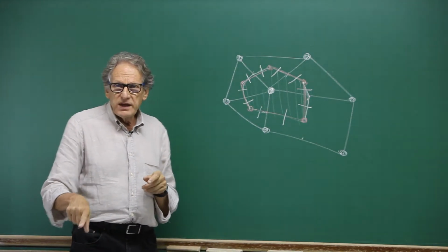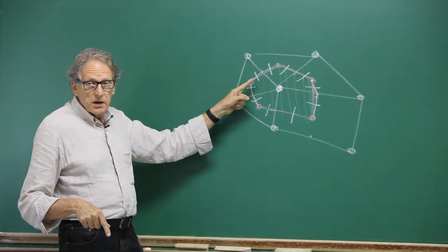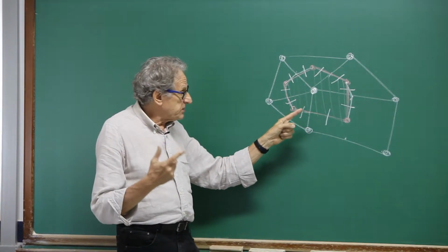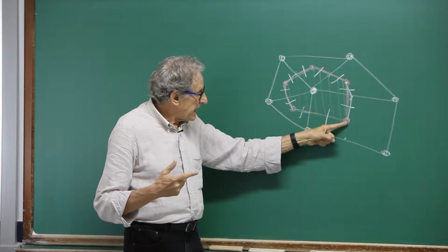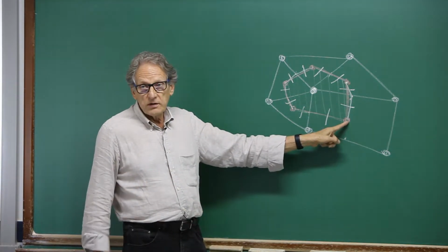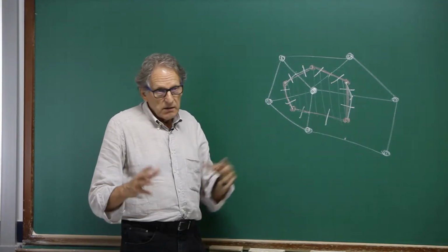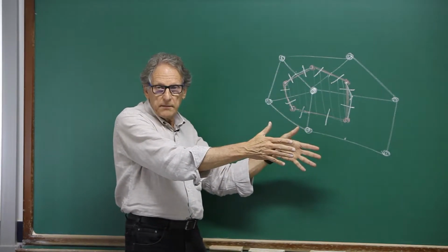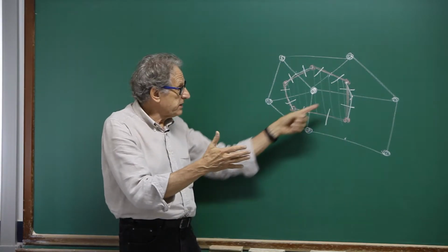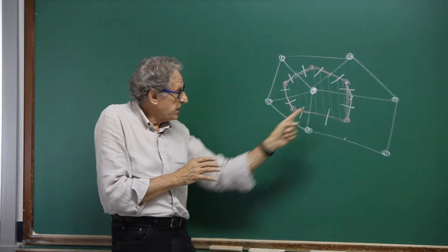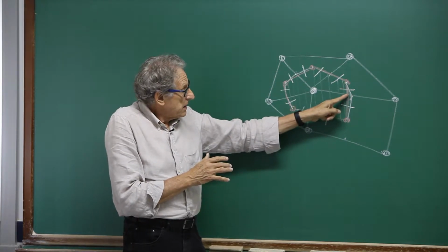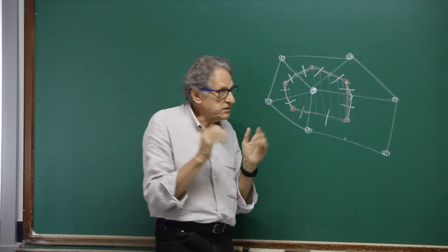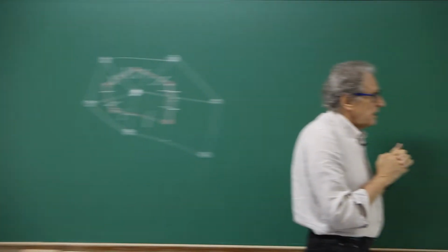Well, it's called element-based because of the construction shown here. But of course, the control volume which arises by joining the centers of the elements with a straight line has the same analysis. The only difference is that you may have some distorted elements, and your straight line is not going to cut the edge in the middle. That's the only difference.